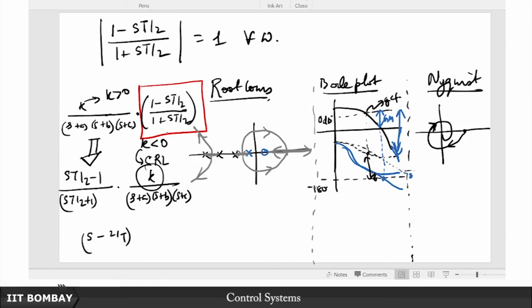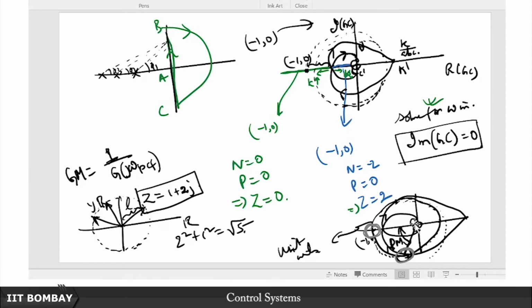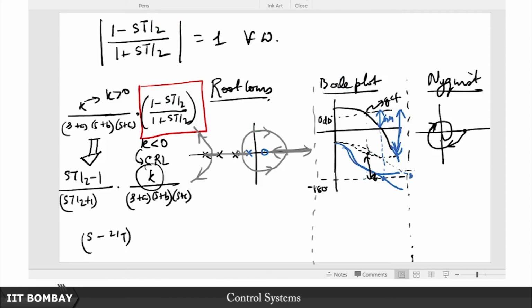So this term had the additional effect of doing nothing but twisting this Nyquist plot around this point, where it is converging to the origin. Instead of converging along the positive imaginary axis, now it is going to converge along the negative imaginary axis, so an additional phase. And this most certainly in the Nyquist plot also is going to show that if you do not have sufficient phase margin and sufficient gain margin to start with, you might very well have already encircled now.